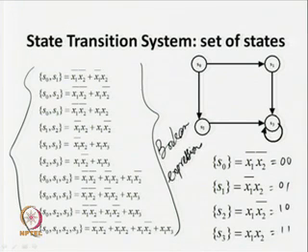Okay. Once we have this particular Boolean expression, then what can we do? We can construct a BDD for those Boolean expressions. Now, you just see that sets of states can be represented with the help of BDDs, or in particular we can say ROBDDs, reduced ordered binary decision diagrams. And we are going to get a unique representation if we stick to a particular variable ordering.